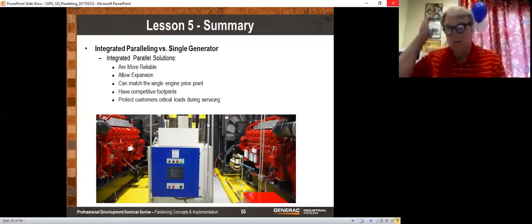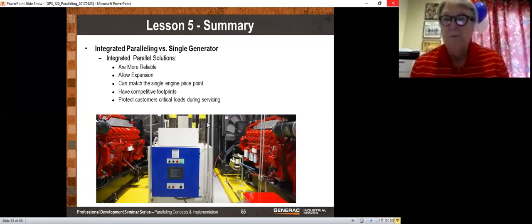That causes the power to go down and eventually will ruin the engine. That is not a problem with parallel generators. It's a problem with diesel generators, and it doesn't matter whether they're paralleled or not. So we generally recommend that once a year, sometimes once every 2 years, you bring in a portable load bank and you run those generators at full load. Wet stacking is caused by carbon deposits, and so we load bank them. We get all those carbon deposits burned out, and we can restore that engine to like new condition.